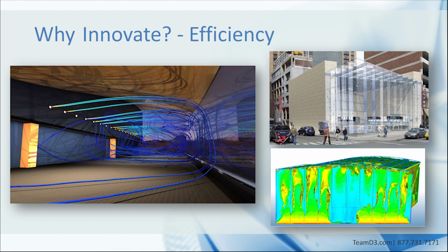The glass wall is naturally exposed to solar radiation, and the challenge was to cause the air to flow in a laminar fashion such that it would not disturb the stratification layer and then wash over the glass wall to absorb the heat during the day and also reduce the buildup of condensation on cold days and nights. To achieve this, slot diffusers were required, but the HVAC provider had never implemented floor slot diffusers in this way and for a glass wall of this height.